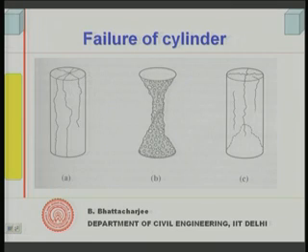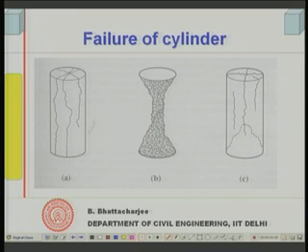Let us look at the failure of cylinder. We have looked at the failure of cube. Failure of cylinder is something like this. You see, initial cracks would be something of this kind. Then if you have applied load, again it is not vertical cracks, although cracks started vertically. At the center you have just vertical portion.